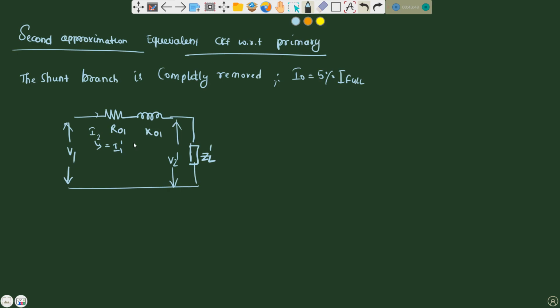There will be a small leakage flux in either winding, about 2%, that we are considering. To account for the induced EMF due to leakage flux, we introduce it in series with the inductive reactances on the primary and secondary side.